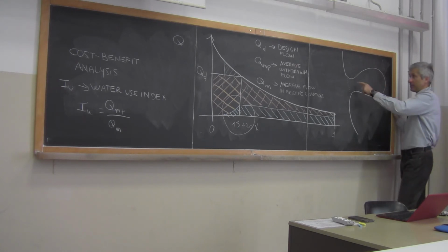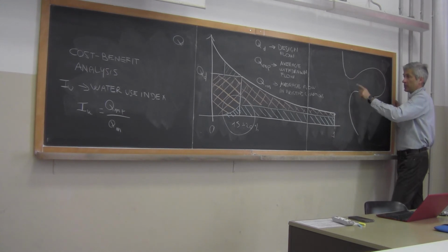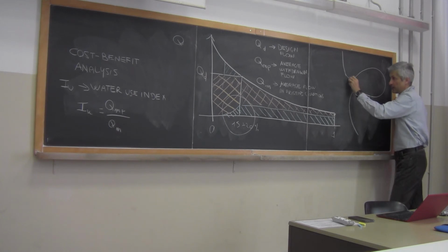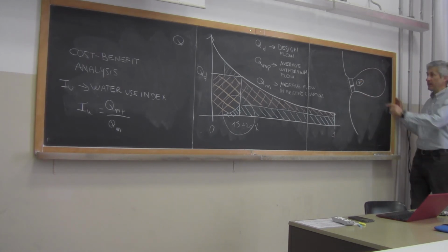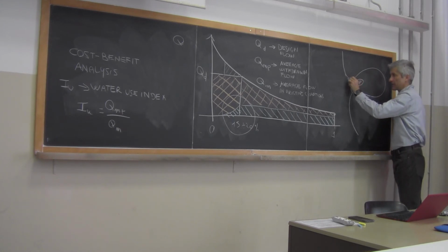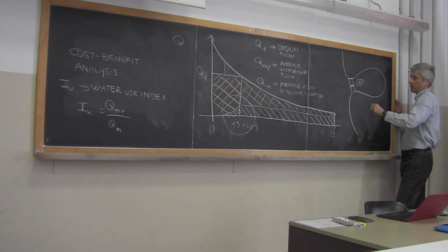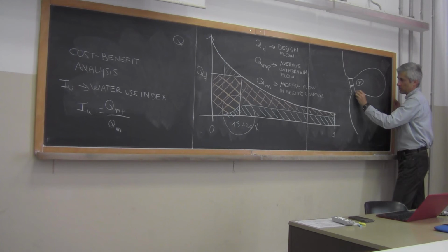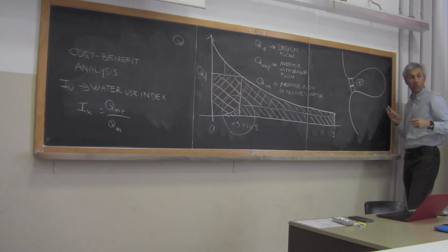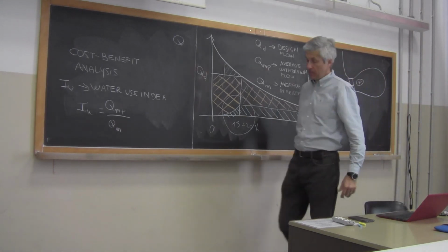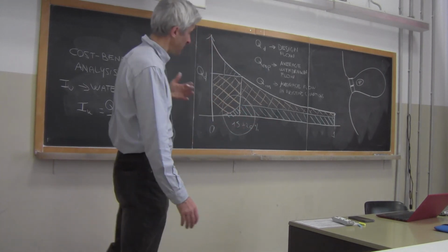So what they did here, given that there is a difference in elevation from here to here, because the meander is quite long, of about a couple of meters, is to build a canal and put a barrage in the canal, and in the barrage there is a hydropower plant. They have a gate upstream, they also built a gate here, and with this gate they regulate the flow that passes through the hydropower plant. And it is indeed a big plant.